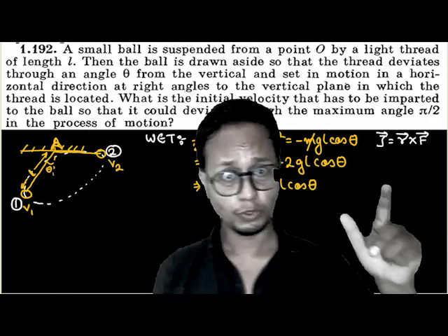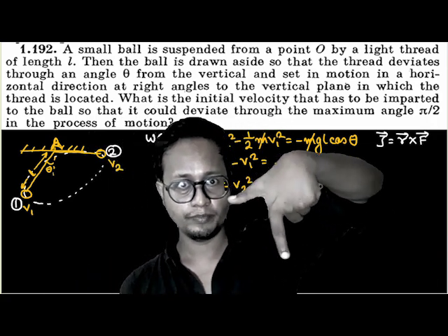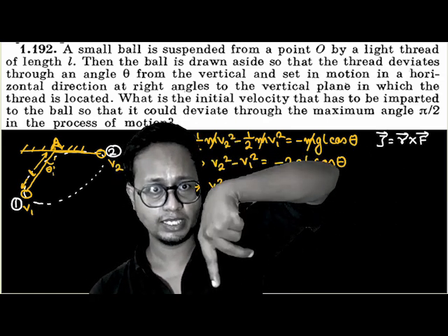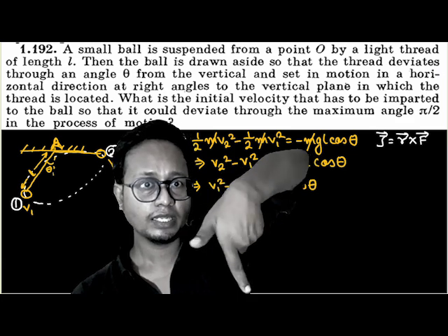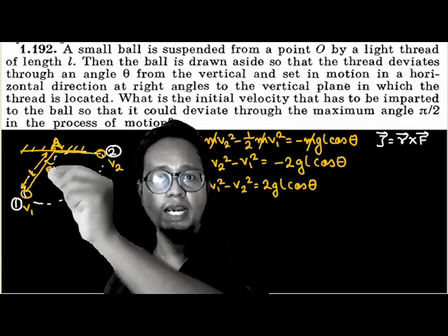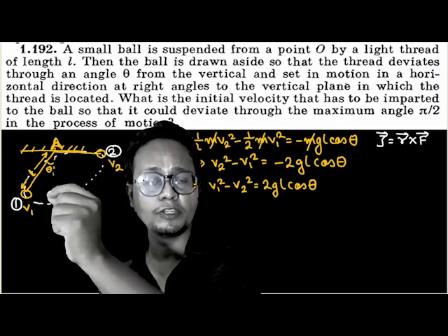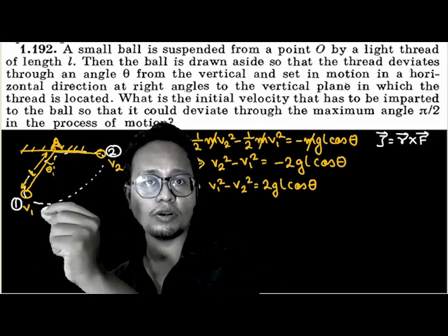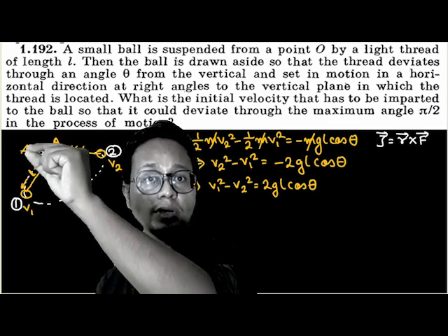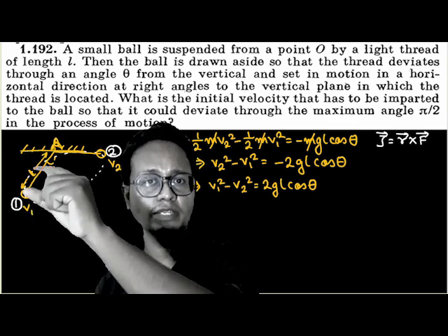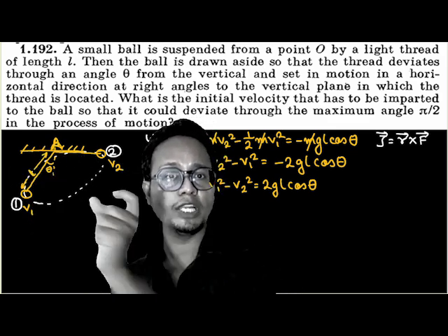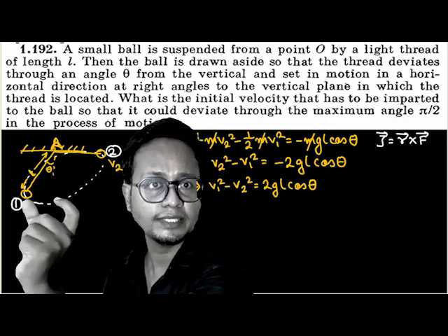So my force is always downward. Doesn't matter what the value of r is. There is no component of torque in this direction. So what about in this direction? R is in this direction. See, when r is in this direction, there will be two components. L sin theta is this much, and L cos theta. Torque due to L cos theta, mg into L cos theta, torque due to that portion would be zero, no? Because the angle between L cos theta and mg is zero. There will be only component due to L sin theta, isn't it?